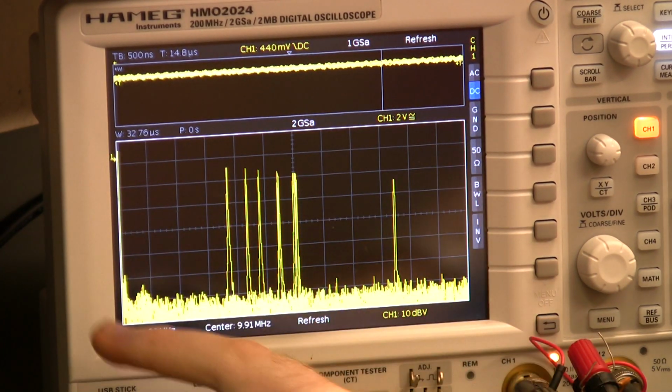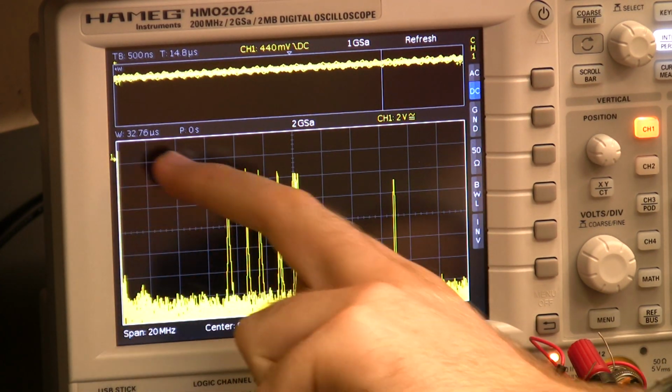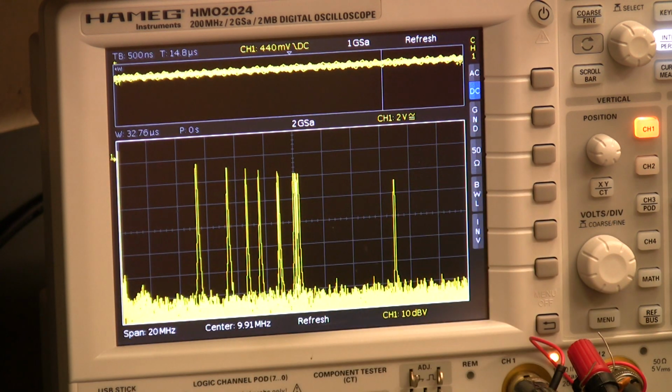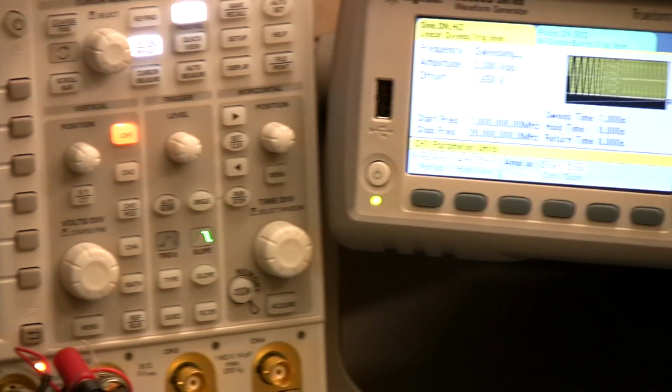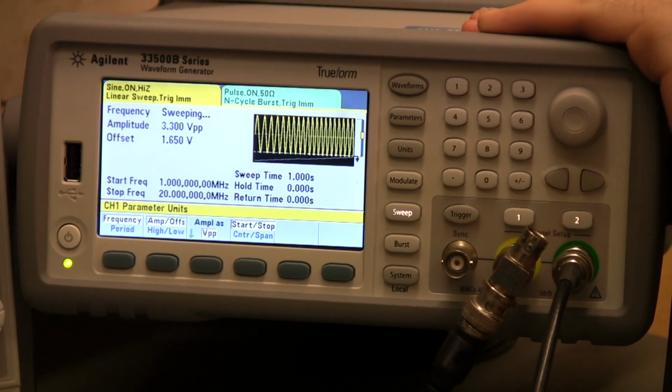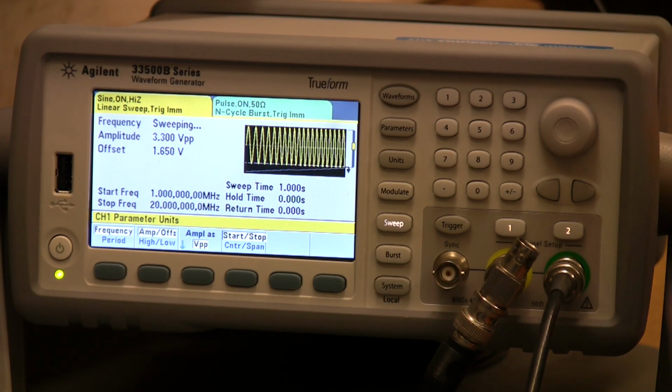As we start to build this up over time, you'll start to actually see a change in height with regards to frequency. So that's a change in amplitude, and you can actually start to build up a filter response using this technique. So the fact that this has got such an accurate response all the way over frequency compared to, as I say, the Rigol when it first came out, the DG1022. There's actually a big bug in it where the amplitude dropped as the frequency got out towards 20 megahertz or so. This one doesn't suffer this problem, so you can actually plot out filter response using this.